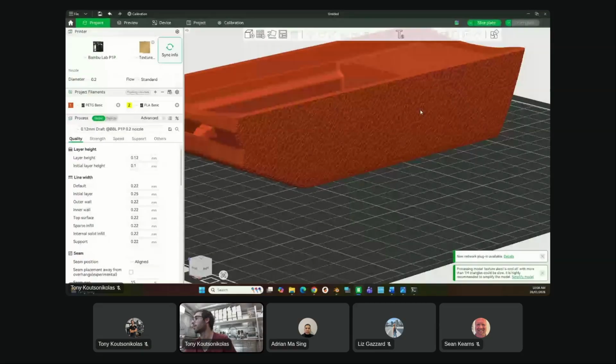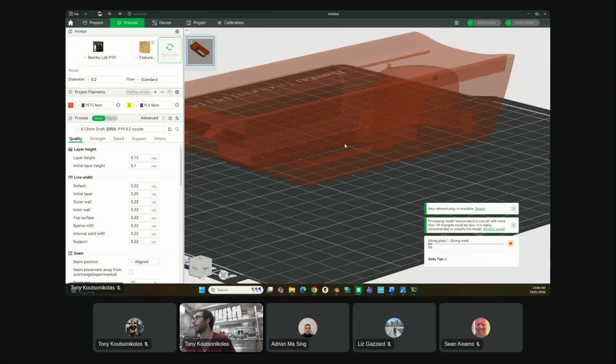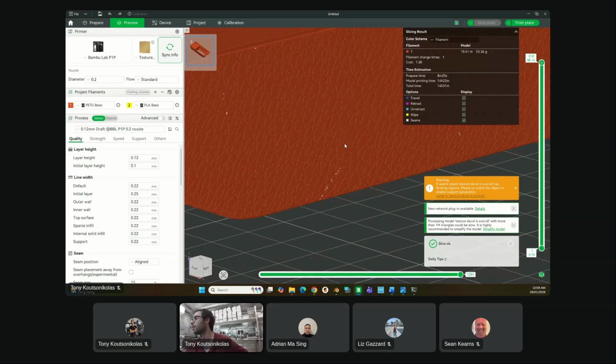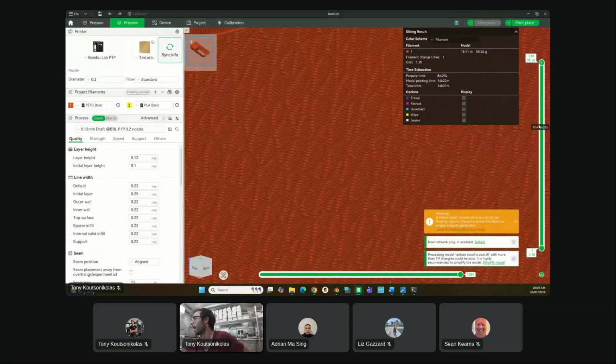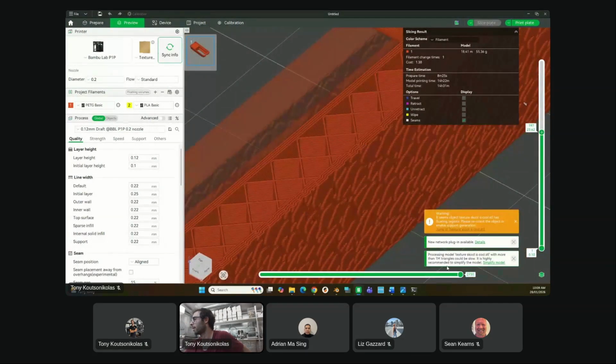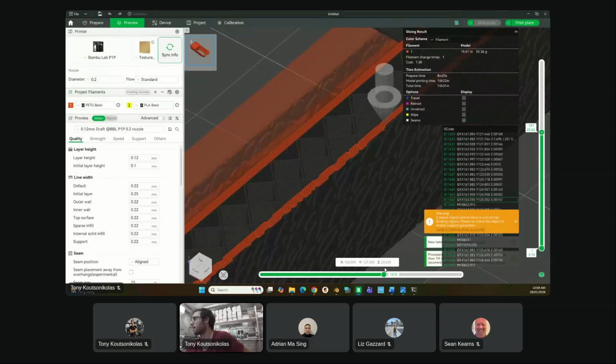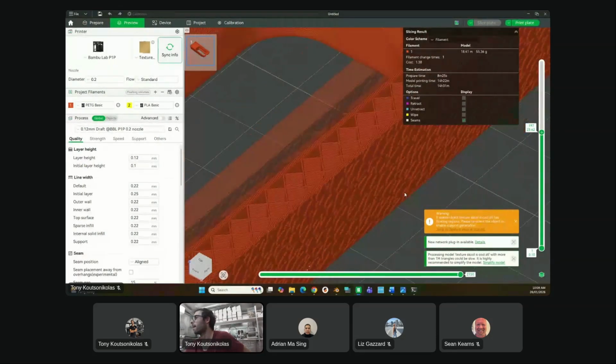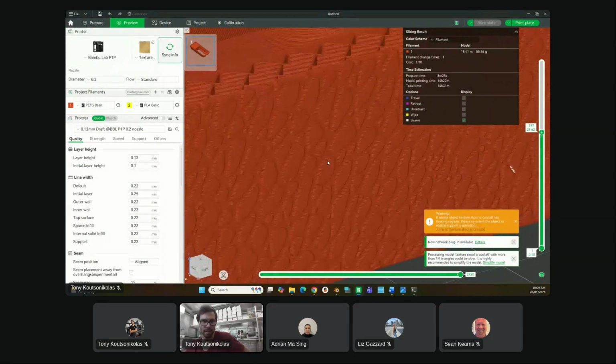So in this orientation, the texture will print really nicely because in the XY direction, it'll create these little divots and little mounds that it'll weave between as it's printing that layer. And it'll actually take a lot longer to print because of that. It can't quickly zoom across and print that wall. It has to slow down and jitter. You can see here, if I zoom in, these are coming out really nicely in this direction, but it's got to jitter around, and that's why it'll take a lot longer to print that part. But yeah, can you guys see that properly?